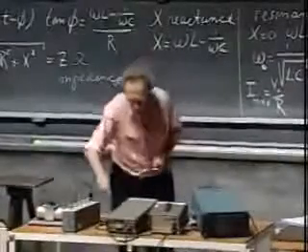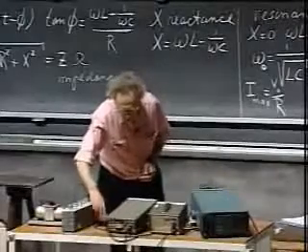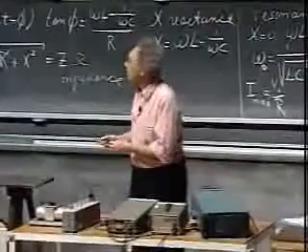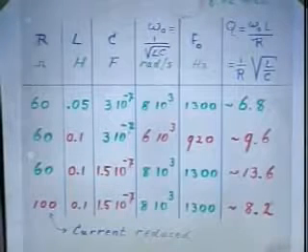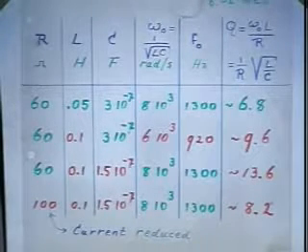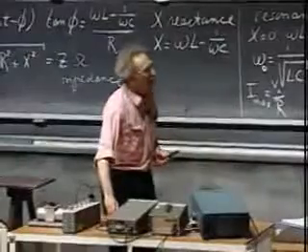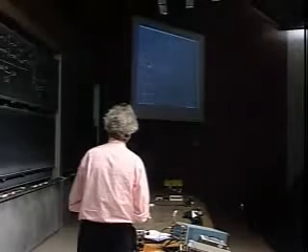And so I go now from 50, oh no, I go from 60 to 100. I don't double it. I can't go any further than 100. But you'll see a substantial reduction. So if you're ready for this, remember this height, and now you see 100 ohms, and it is much lower. It was this height before, and now it's only here. But notice the resonance frequency has not changed.